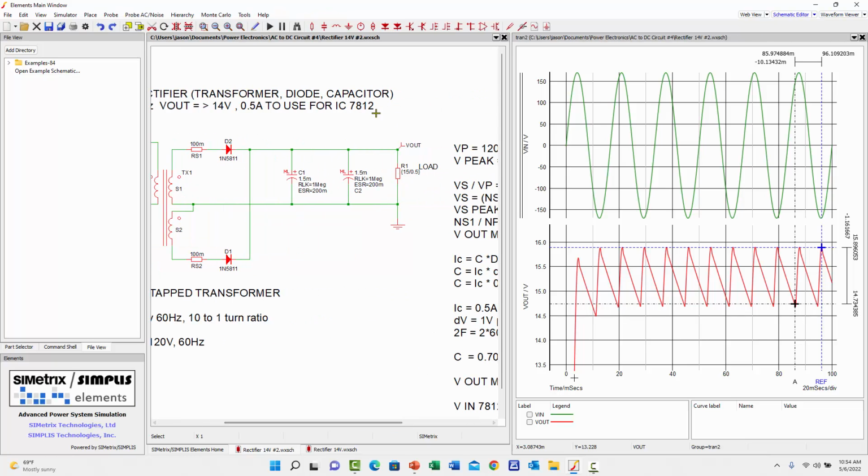So this is my secondary circuit, which is important so that we know how to select the capacitor for the design. And as you can see, inside the tantalum cap there is an internal resistance we call ESR. This ESR contributes to the ripple voltage. That's why you're seeing it a little bit higher than we expected when we calculated.